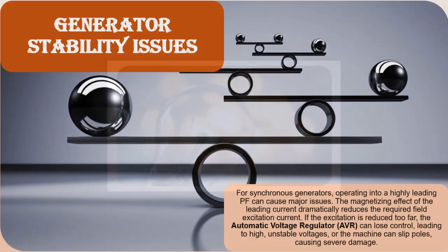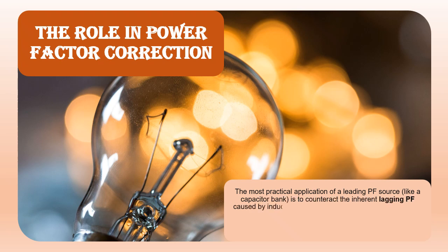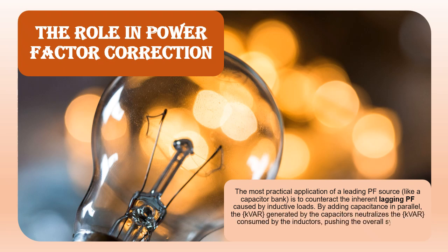The role in power factor correction. The most practical application of a leading PF source, like a capacitor bank, is to counteract the inherent lagging PF caused by inductive loads. By adding capacitance in parallel, the kVAR generated by the capacitors neutralizes the kVAR consumed by the inductors, pushing the overall system PF closer to unity.